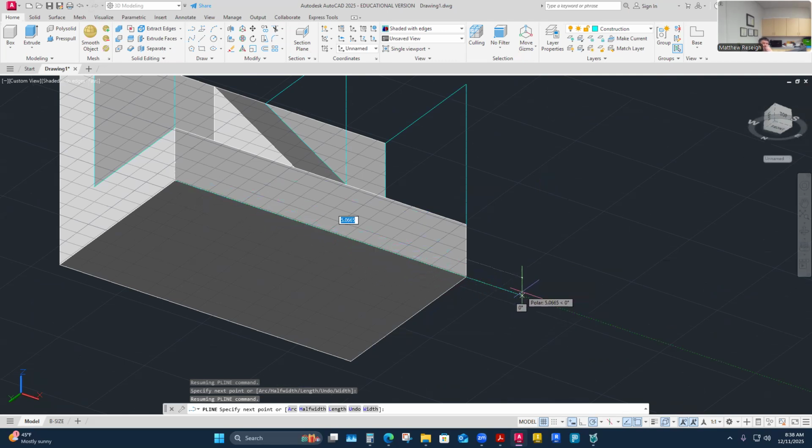I like that my cursor looks like a 3D cursor, it has all the 3D axes there. So this just helps me know that I'm snapping in the right direction along that plane. From that point there, I'm staying in that plane. If I stay on my object, it can be a little hard, and I can grab an O snap that I didn't mean to. But really I'm just trying to come over here 3/4 of an inch, which is right there, and then I can come down.